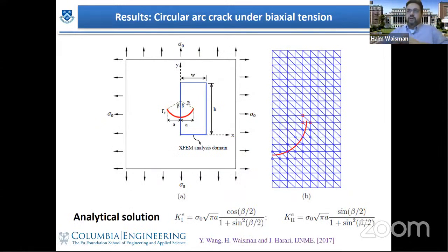Another example where there's an advantage of this method over the J-integral formulation is in a curved crack scenario. If you're using a J-integral formulation, especially the domain version of J-integral, it has been shown in the literature that if you have crack curving, then the domain version of J-integral diverges at some point, unless you introduce additional features there.